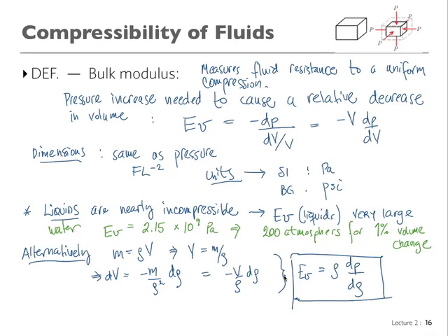So compression of liquids is not very interesting, because of the very large bulk modulus, nothing really happens. You have to apply incredible amounts of pressure to do anything with it. But compression of gases is quite interesting. There's also a whole branch of fluid mechanics that studies compressible flow, the compressibility of gases, and you have to bring in a lot of thermodynamics in that case. The compressibility phenomenon depends very much on how the process of applying pressure is carried out.